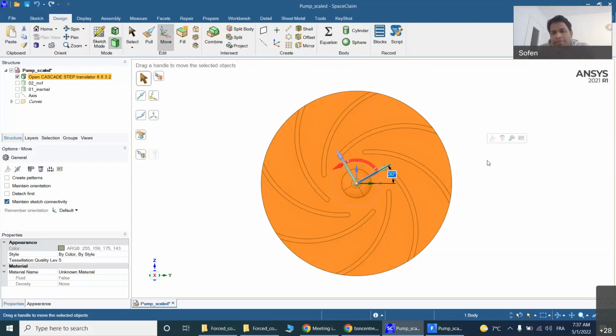But if you have 3 blades, 4 blades, 5 blades, and you take the MRF flow field with respect to a particular position, then you either under predict or over predict the flow, right? To avoid such things, normally we do 4, 5, 6 different positions of the blade, save the different meshes, then do statistical averaging over the different positions to get the mean flow rate.